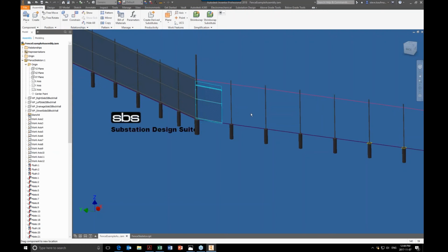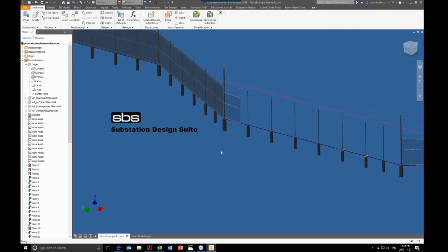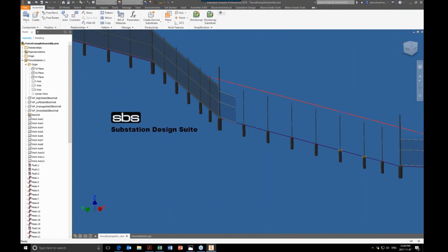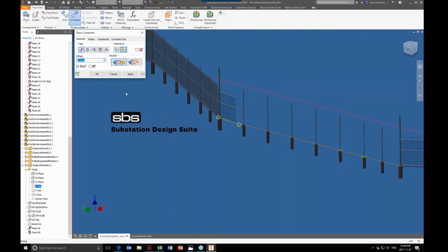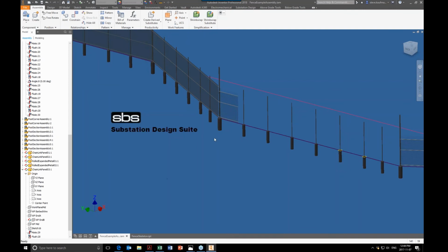It's not aligned yet, so let's align it to my skeleton. So let's come back down here. I know how I've drawn this, so I can take that axis and constrain it to my skeleton. Now everything's constrained. I can't move that at all, right? But let's look at what I'm talking about with adaptive. We have our little blue-red circle, meaning it's adaptive.